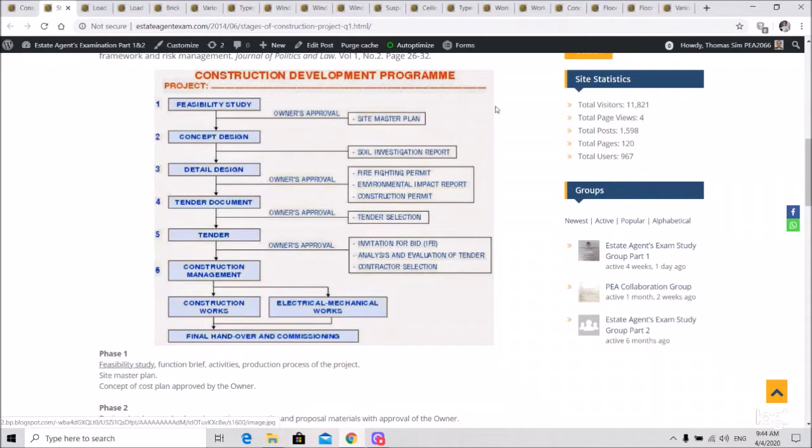For example, some of the land, because there were potholes or big holes before, maybe mining land, needs landfill. The landfill in some places is at least 20 years old. So all these need to go through tests and feasibility studies before constructing a building on top of this plot of land. All those things need to be decided.